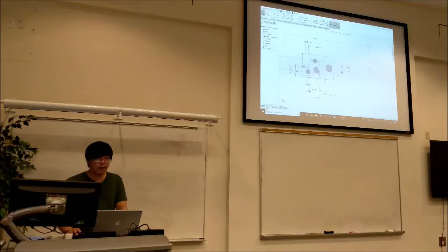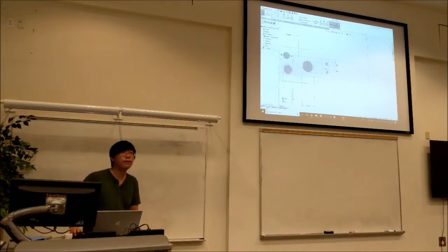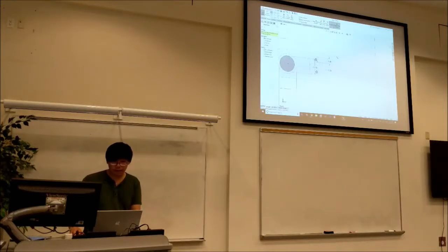For our robots, it'll obviously depend on how you do things, but we do a standard hole pattern on our tube. It's basically just 1/2 inch from the side, then a hole, then another inch, then a hole, and then 1/2 inch to the other side. So we have 2 holes running across our entire 2x1, and that makes it really nice to move the positioning of things later on if we need to. A really easy way to model that hole pattern is just by drawing 4 lines here.